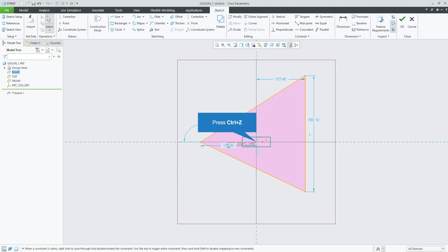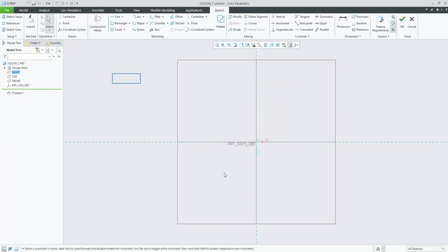So now let's Control Z twice. And we'll go to rectangles. The first rectangle is a corner rectangle. So this one you click anywhere. Let your mouse move, not drag. It's just click and move. Click again, and your rectangle is created.